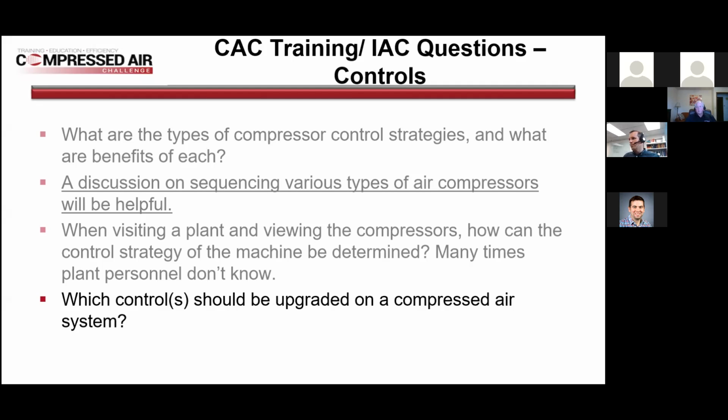I've had situations where I had real old controls that I wanted to upgrade. I had old recips that were running with centrifugals. The problem I had is the centrifugals ran base loaded all the time, and the recips cycled with the old pneumatic controls just fine, and I could never cost justify it. So a lot of it you still have to remember has to be cost justified when you go through and put in a control system.